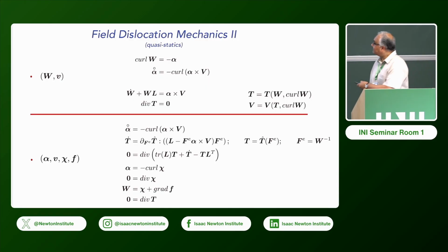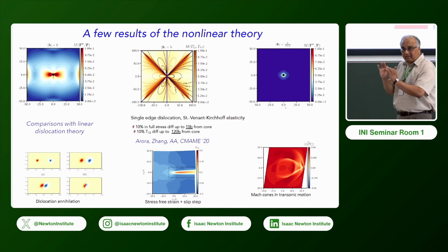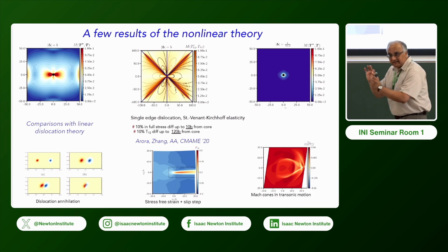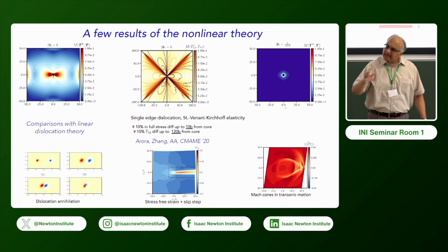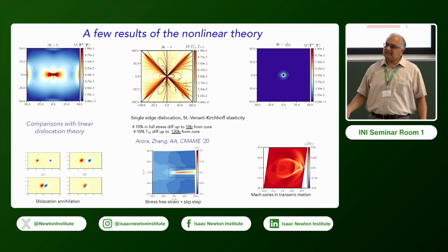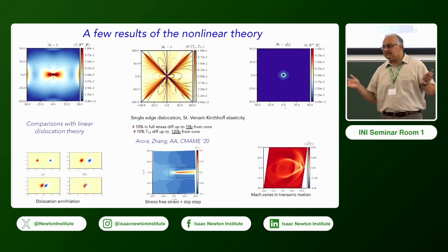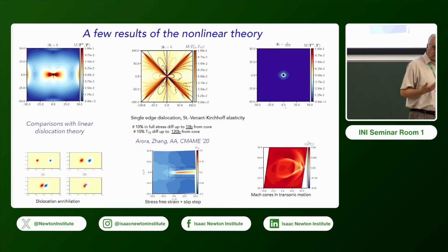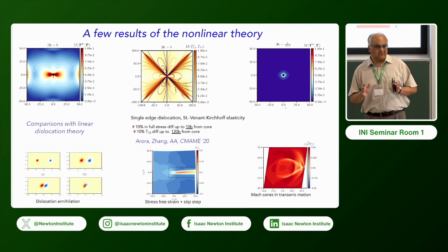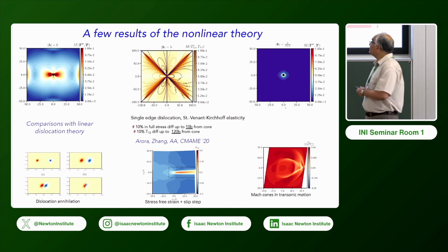Okay, so now let me show you some results at the microscopic level, meaning you're resolving every dislocation. One question is, I've heard this all my life: apparently, if you're doing dislocations, you do linear elasticity, and beyond that, apparently, unless you do quantum mechanics, nothing matters. Linear elastic fields are very, very good, just away from the core. If you've grown up with general continuum mechanics, this doesn't quite sound right, because there are pretty high stresses and strains. So what? Nonlinear elasticity doesn't matter?